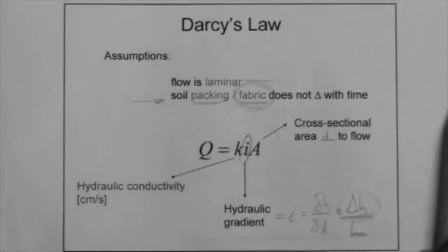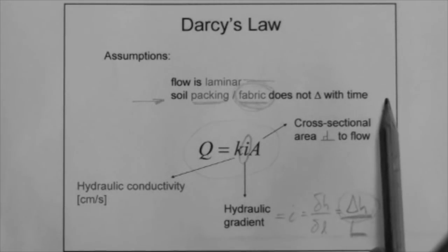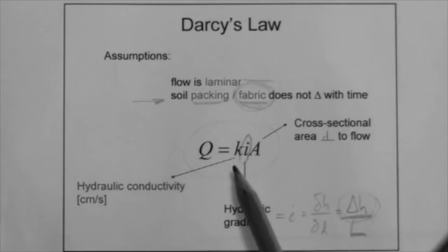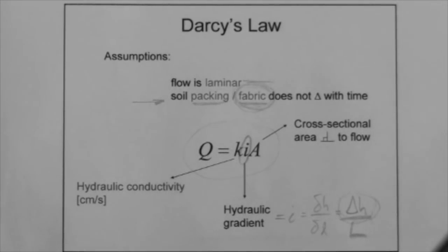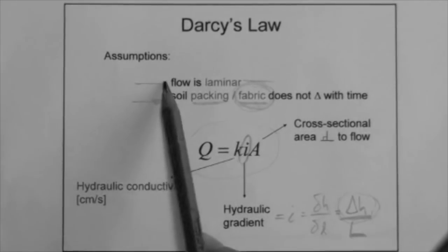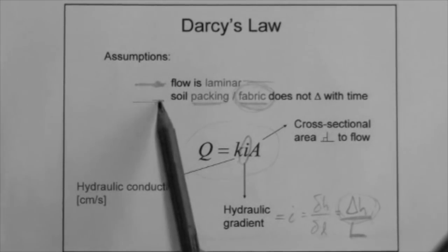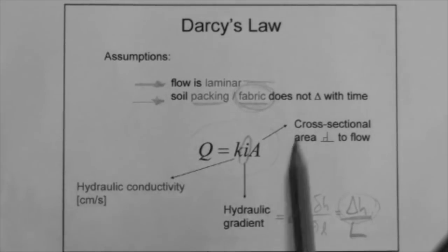If it changes because of the flow, or changes because of time, maybe some particles are decaying while you do the test, then the K that you measure is not really a true K because the soil is changing. So these are the two main assumptions that we need to fulfill for applying this equation.